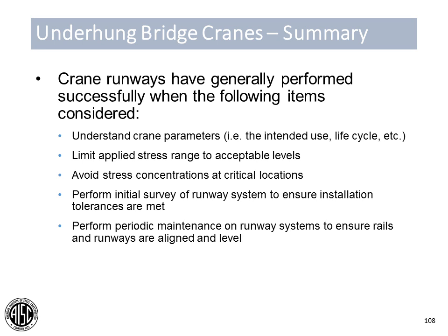But these runway systems have performed very successfully when you understand the parameters of the crane, how it's going to be used, what the life cycle is of the crane system. If you limit the applied stress ranges to acceptable levels for fatigue, you avoid stress concentrations at very critical locations by maintaining a continuous and uninterrupted tension flange. If you perform initial survey of the runway to make sure the installation tolerances are all met, and then also perform periodic maintenance and make sure you educate your owner that they need to be performing periodic maintenance.